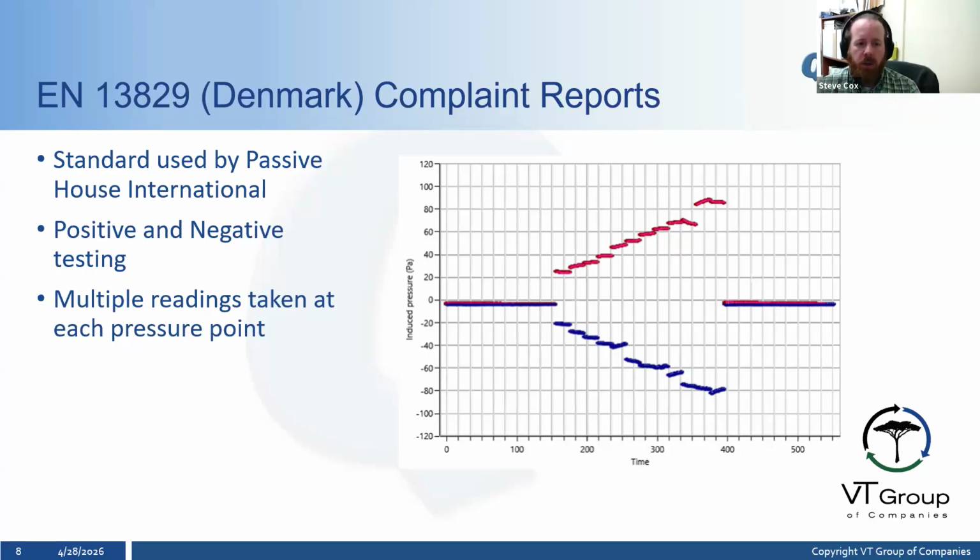Okay. So on this one, as you can see, we have our negative pressure testing relative to outside. So we have the fans blowing out air from the building in this instance, and then we're blowing air into the building in this instance. So we have to flip the fan physically around and blow air into the building.